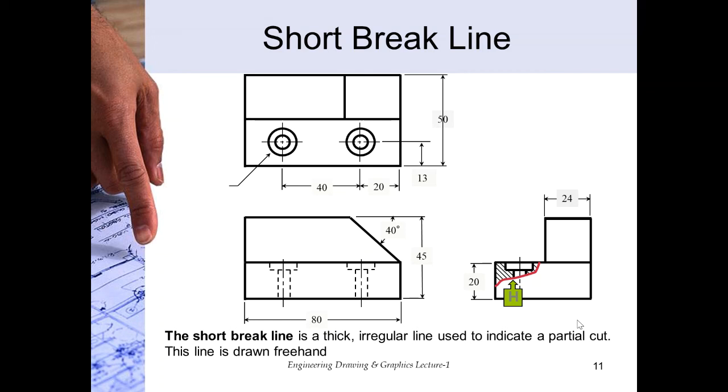Now we have a short break line. The short break line is used very rarely, but it's also important. A short break line is a thick irregular line used to indicate a partial cut. The line is drawn freehand. The line that is drawn is freehand drawing. There is no particular